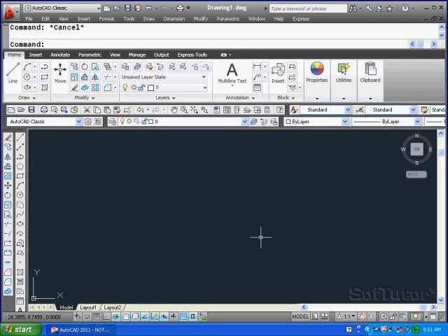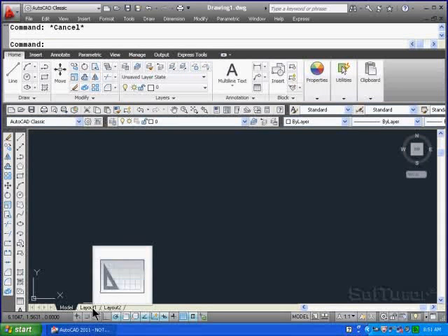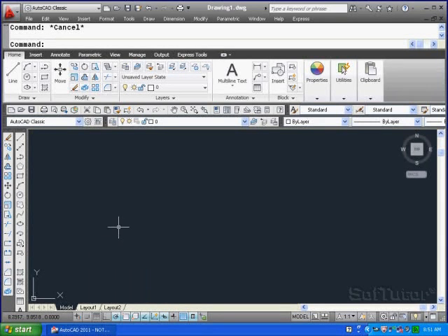First off, let's just look at the area here. You see this is a model space environment, this is the real world environment, and then down below you'll see that you have a model tab which indicates that that's where we are. Down below is Layout 1, Layout 2, and this can be a number of layouts. Like an Excel spreadsheet, we can add more tabs down below. But this is where we will move over to a paper environment, the scaled environment.